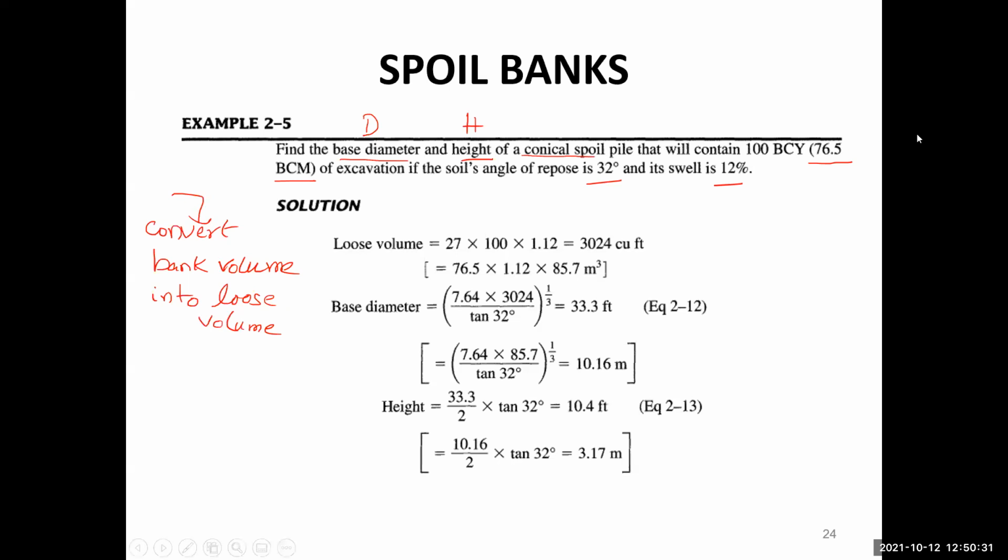If we just use the bank volume over here in this calculation, then that is not the original condition, because once you excavate the soil from its bank condition, the soil expands, and that soil is converted into its loose condition. So therefore, some swell percentage should be added, and then the loose volume will be used.